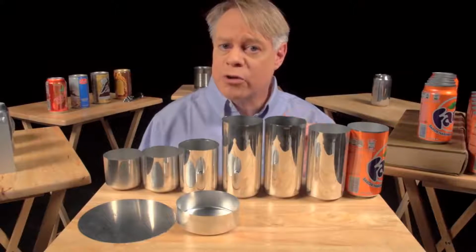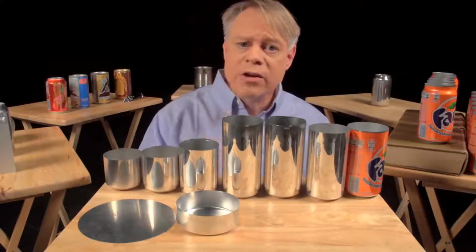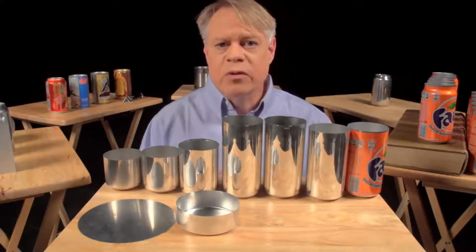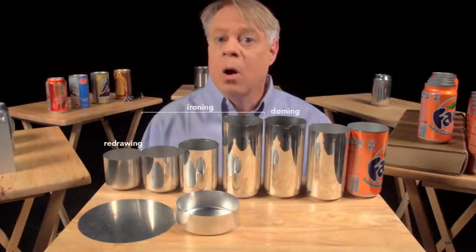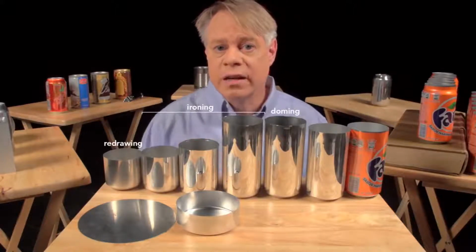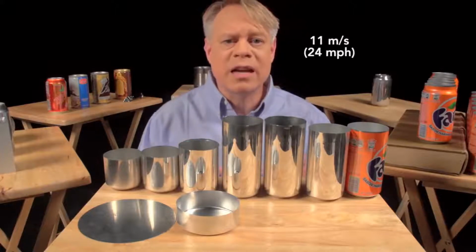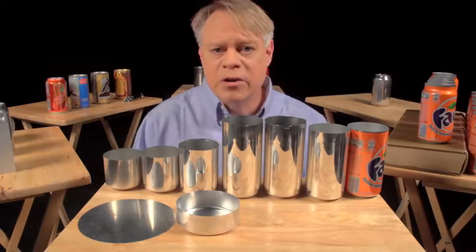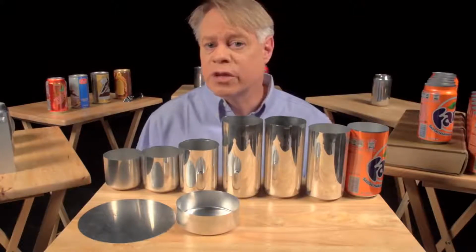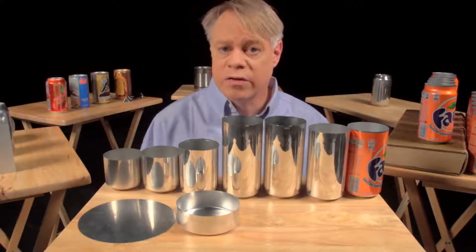These numbers help troubleshoot production problems in the factory. In that factory, the manufacturing of a can takes place at a tremendous rate. These last 3 steps, redrawing, ironing, and doming, all happen in one continuous stroke in only 1/7 of a second. The punch moves at a maximum velocity of 11 meters per second and experiences a maximum acceleration of 45 Gs. This process runs continuously for 6 months or around 100 million cycles before the machine needs servicing.